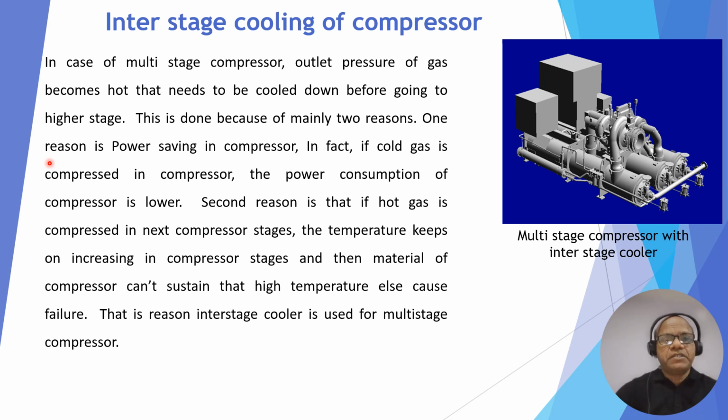One reason is power saving. In fact, if cold gas is compressed in the compressor, then the power consumption by the compressor will be lower. So if low temperature gas goes to the higher stage, then the compression power consumption for the next stage will be lower.